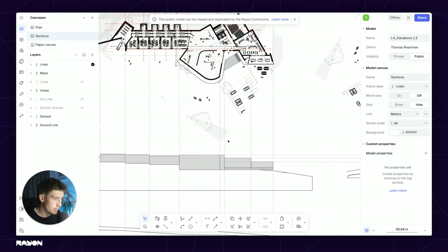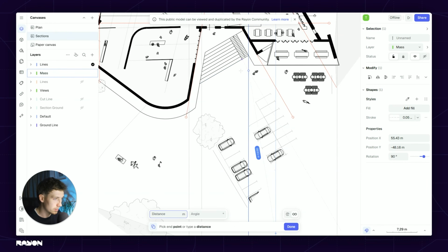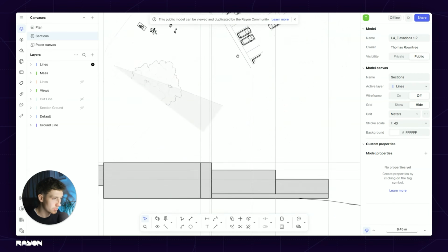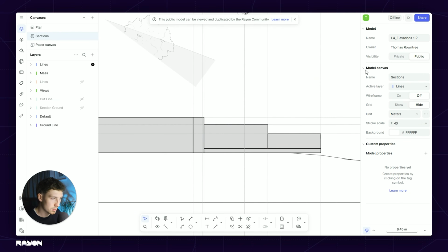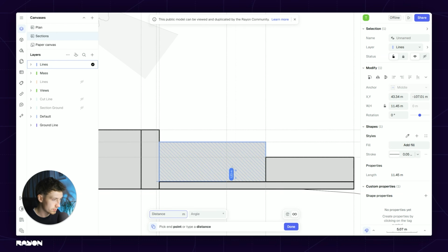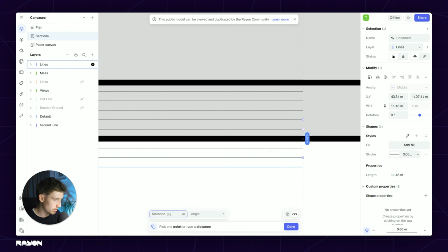The first one is going to be the steps. So I'm going to start drawing the steps. If I identify the corner of the steps, which is roughly about there, let's then do a line. And we're going to offset this up by, let's say, 0.2 mil. And maybe it actually comes down into the slope a bit, so let's just copy that down.